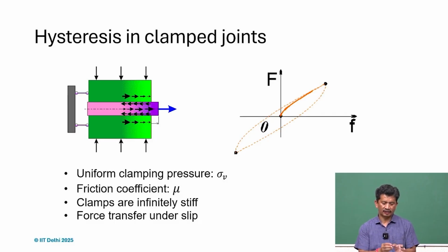Nevertheless, even if there is no apparent motion, there can still be hysteresis, and that happens because of the micro slip. So we don't see it, but because of the nature of the joints, we encounter hysteresis, and the moment we have hysteresis, we'll have a positioning accuracy problem.